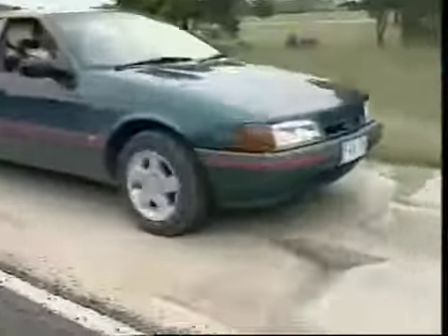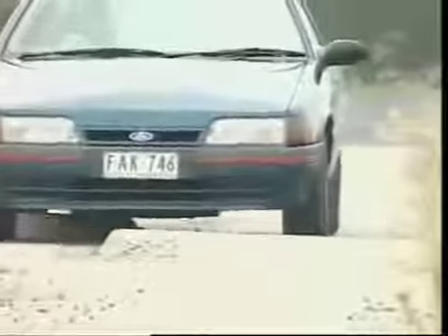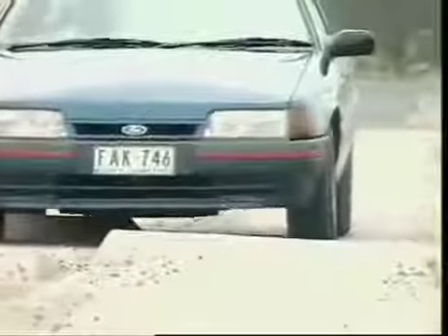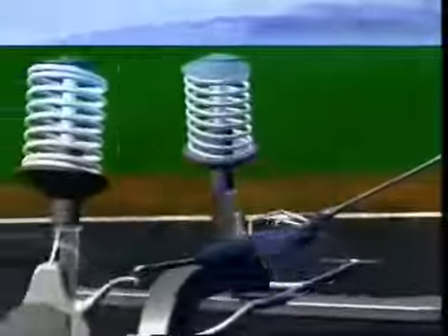The size of this reaction force depends on the unsprung mass at each wheel assembly. The sprung mass is that part of the vehicle supported by the springs, such as the body, the frame, the engine, and associated parts. Unsprung mass includes the components that follow the road contours, such as wheels, tires, brake assemblies, and any part of the steering and suspension not supported by the springs.